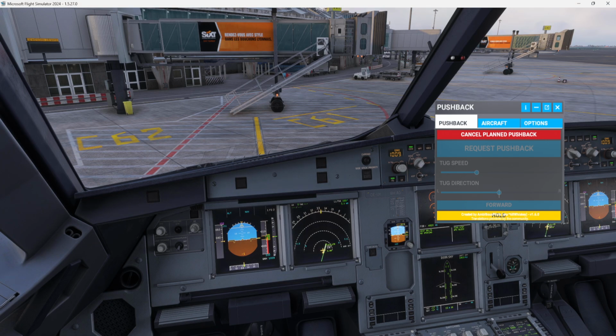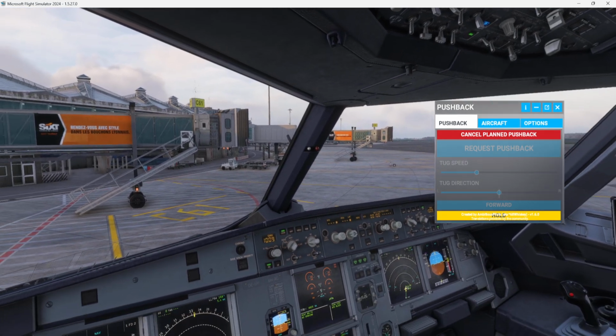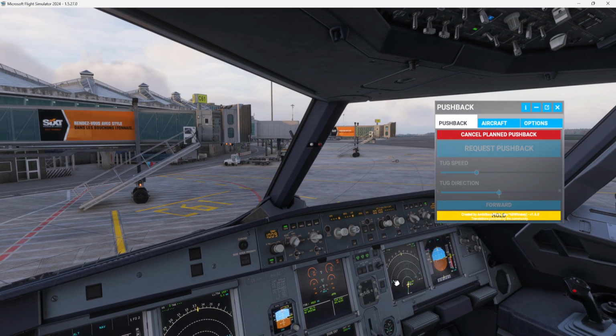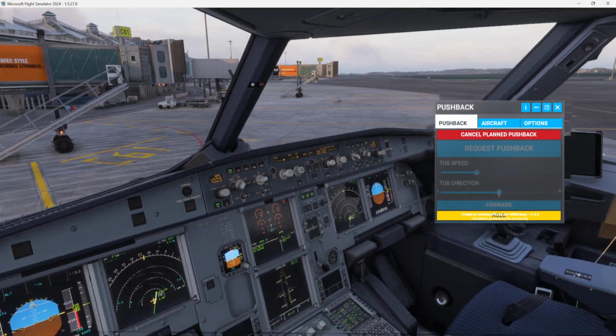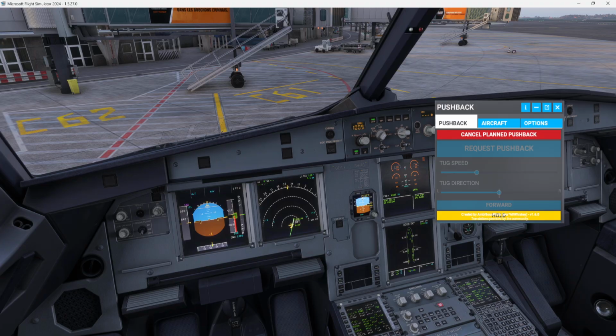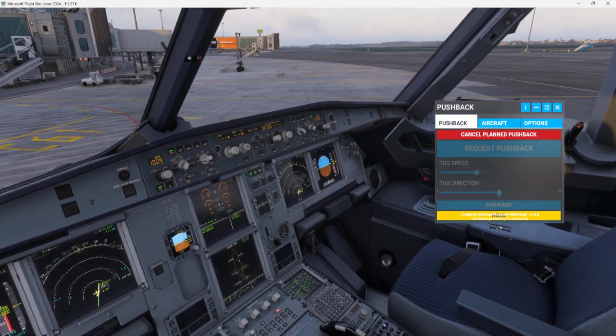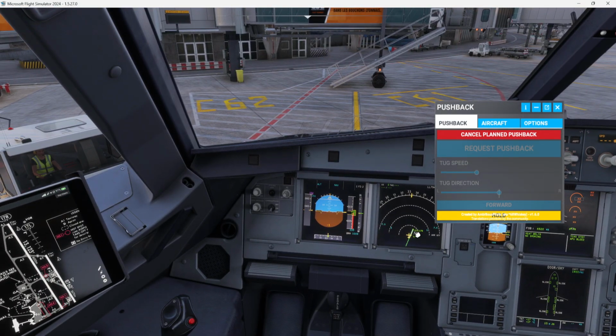So we do the cockpit preparation checklist. We have gear pins and covers removed. Fuel quantity 4.8 checked. Seat belts on. I can see it. We double check over in the overhead panel. ADRs are in NAV position, and baro reference QNH 1009, cross-checked. Cockpit preparation checklist completed.